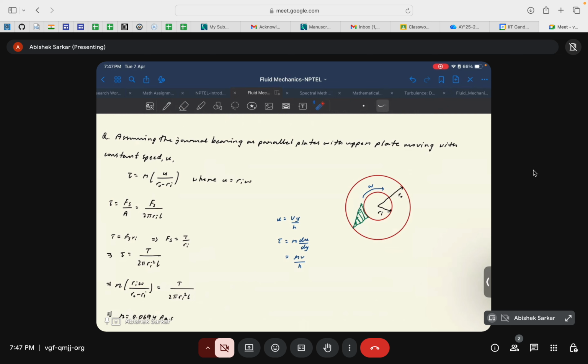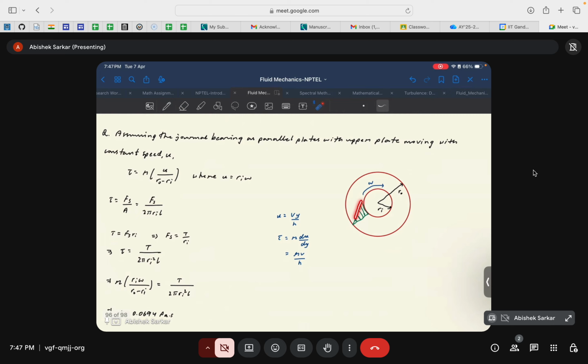Since the inner cylinder is rotating, the fluid attached to its surface moves with it, but relative to the stationary cylinder the fluid will have a certain velocity, which generates the velocity profile. This profile is to be considered linear because the gap between the two cylinders is very small. It's only 0.5 millimeter, right? So let us see what happens.